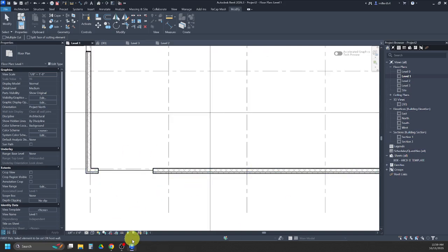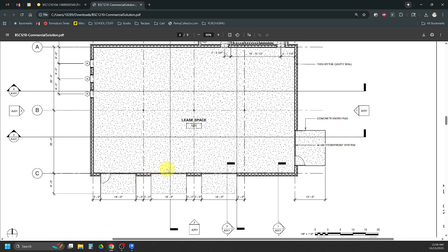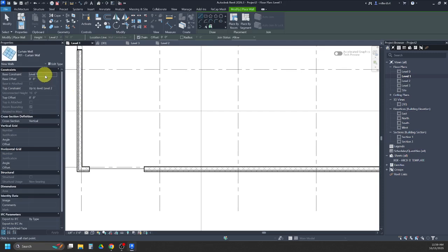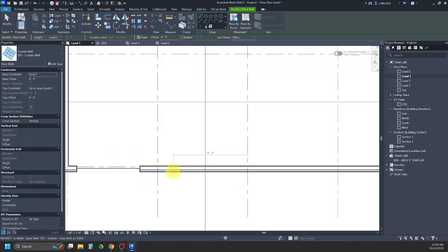I think there's just 2 more on this side. Yeah. I'll put these ones in and then cut them simultaneously. But these ones, we will be able to kind of measure it with witnesses to these grid lines, so we can actually place them a little bit easier. So again, I'll start the wall tool. I'll just keyboard shortcut WA, leaving all my constraints alone.